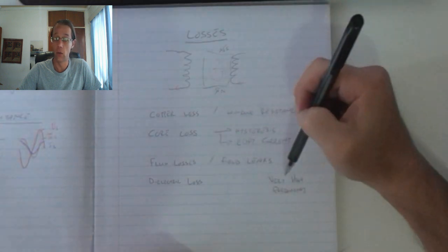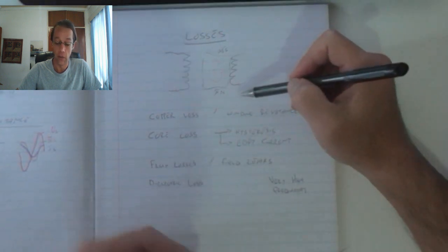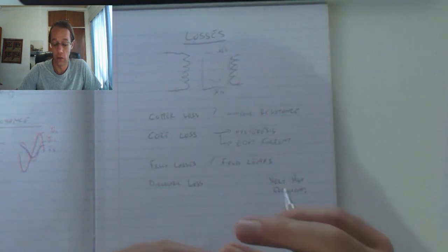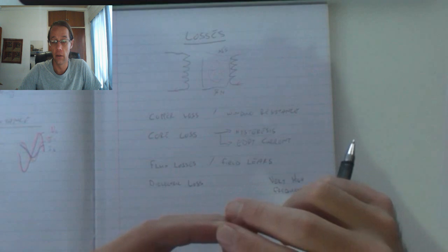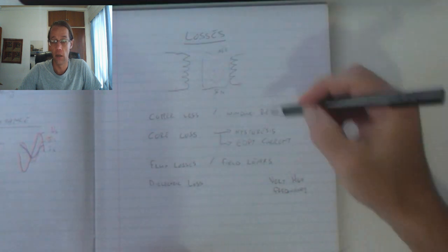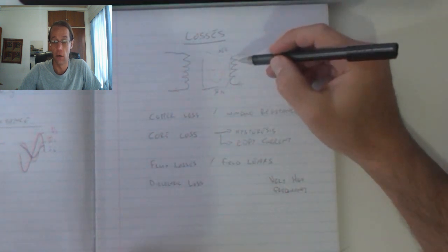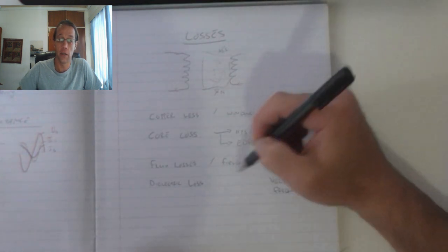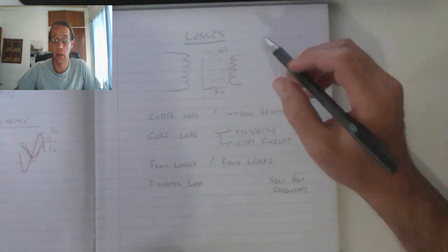Basically, at a very high frequency, the windings will cause a capacitance to form between the individual loops. Those capacitors literally serve as an AC bypass for the current that wants to flow through the coils.